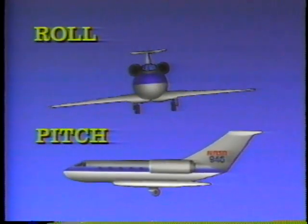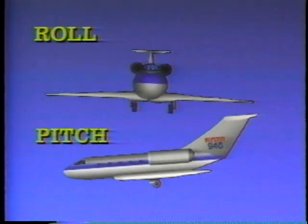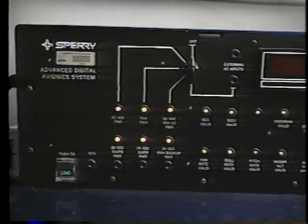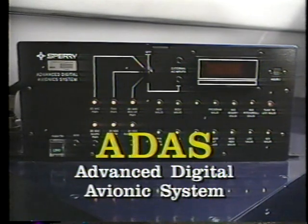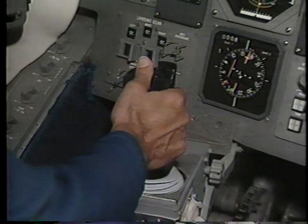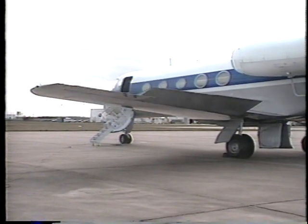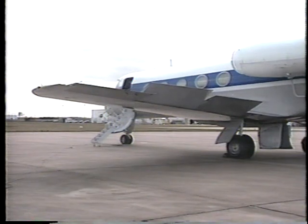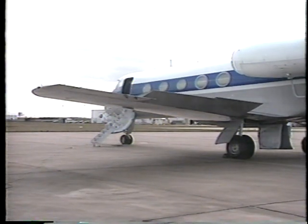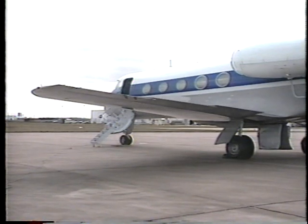Moving the RHC generates signals that represent roll and pitch movements. The signals are fed into the onboard computer, known as ADAS, the Advanced Digital Avionics System. ADAS translates the astronaut's hand movements and electronically moves the aero surfaces to the desired positions. ADAS then checks the aircraft to verify those movements. If a correction is called for, ADAS makes the adjustment within milliseconds.